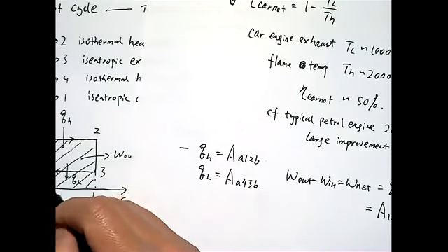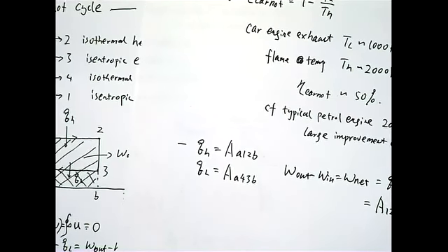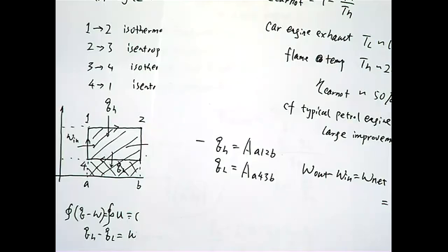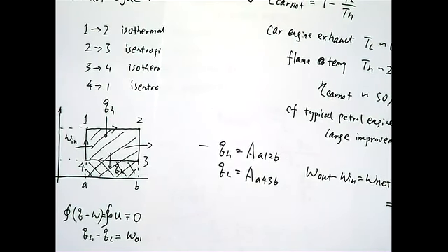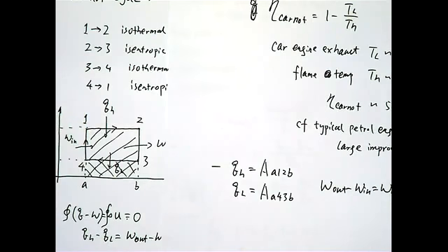All right, so this cross area would be the QL, and the box or rectangular area would equal the net work, not the input or output, but the difference between these two. We are using the TS diagram throughout our cycle analysis. Although there are different ways to plot the cycles, in this study we just use the TS diagram throughout the 3 cycles we're going to study.